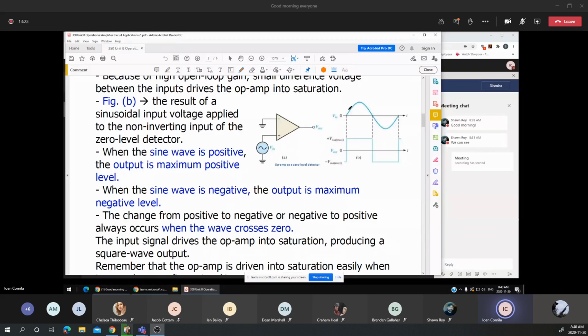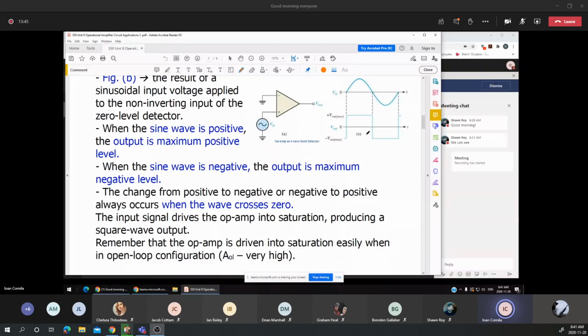Going back to the initial state, if the voltage Vin is just tiny above the zero voltage or the reference voltage, which is zero or ground, the output voltage will reach the maximum or the saturation. For any other voltages greater than zero, it will stay on the maximum saturation voltage.